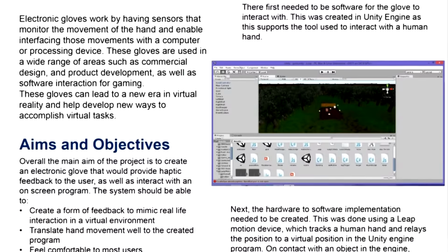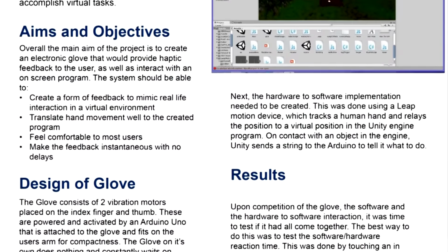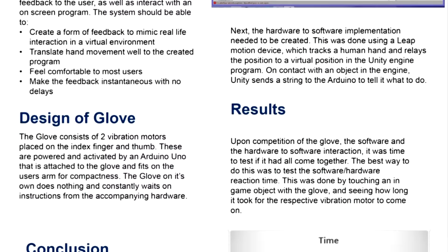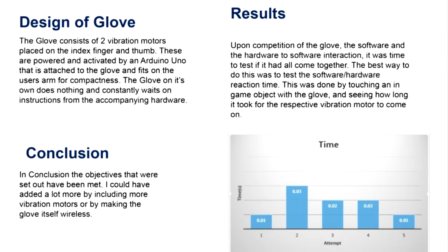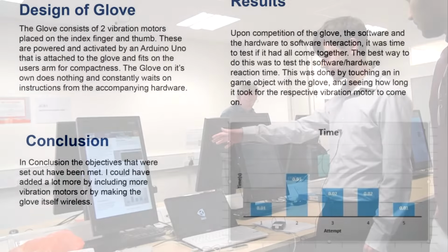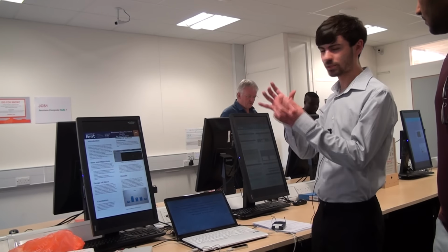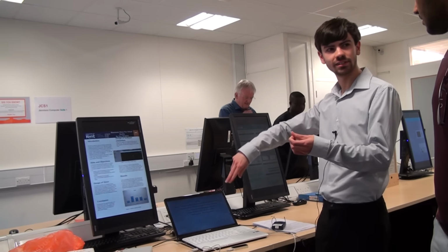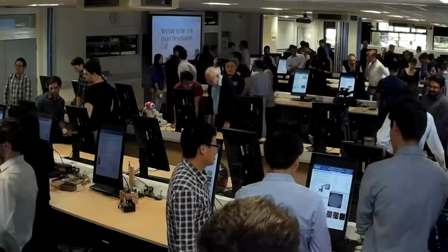And what it does is it checks which object, so which finger on the hand. The way the game works is it can check colliders on each finger, bone, hand, all that sort of stuff. It checks which one is in contact, reads in the serial bit there, whatever I've decided to send to it. Then it turns on the relevant feedback at that point. So if it was the thumb, it sends a T down there, a string, picks up that it was a T, turns that on for a split second, checks again. So it'll just keep polling until it does it.